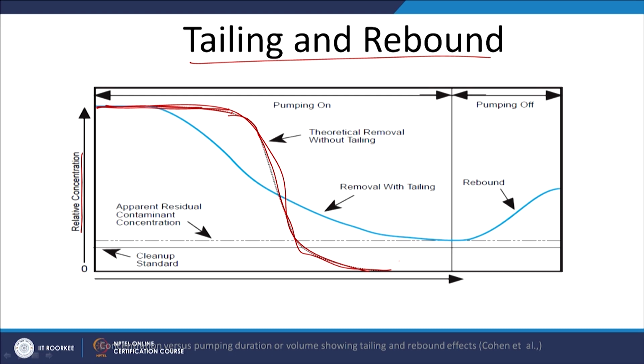Nothing out there. But for slow contaminant release, hydrophobic compounds, NAPL desorption or adsorption onto soil and so on, you will have tailing. Again, what does that do? Increase the time required, and also rebound, which makes it impractical for most pump and treat options, right. In this case, obviously the PRBs are a pretty good option now, right.